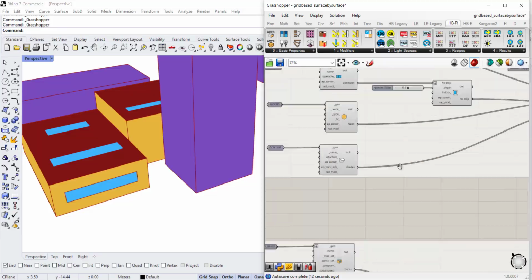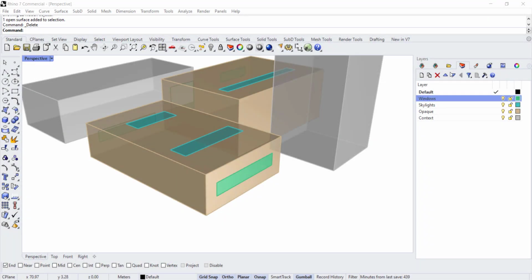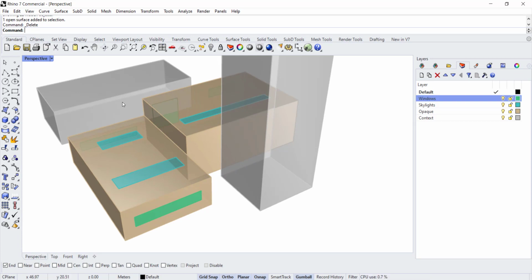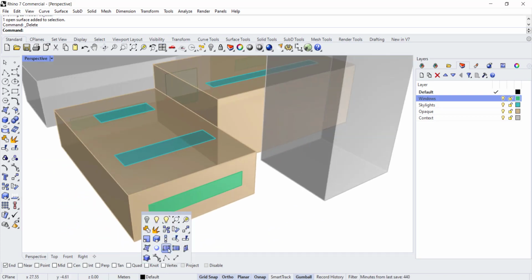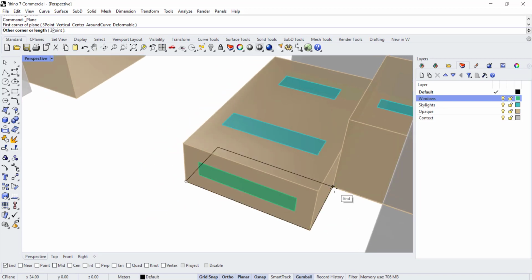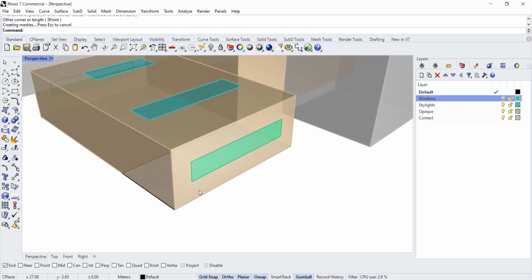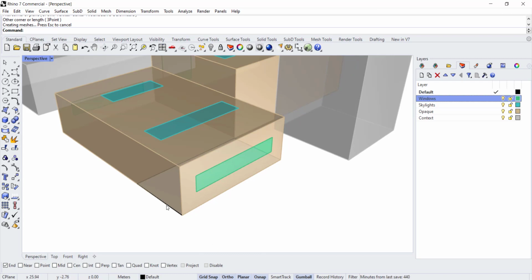Okay, and that's all you're adding for the room when you have rooms already set up using the HB Room from Solid workflow. The second way to create a sensor grid is a little bit more flexible. Say you don't want to test a whole room, the entire volume. You just want to test a certain portion of a room. So you can start by drawing a surface in Rhino that replicates the approximate area that you want to test. I'm just going to create this geometry, and this is the area that I want to test. I don't want to test the whole room and run a really long study. I just want to do a quick study only in the daylit zone.